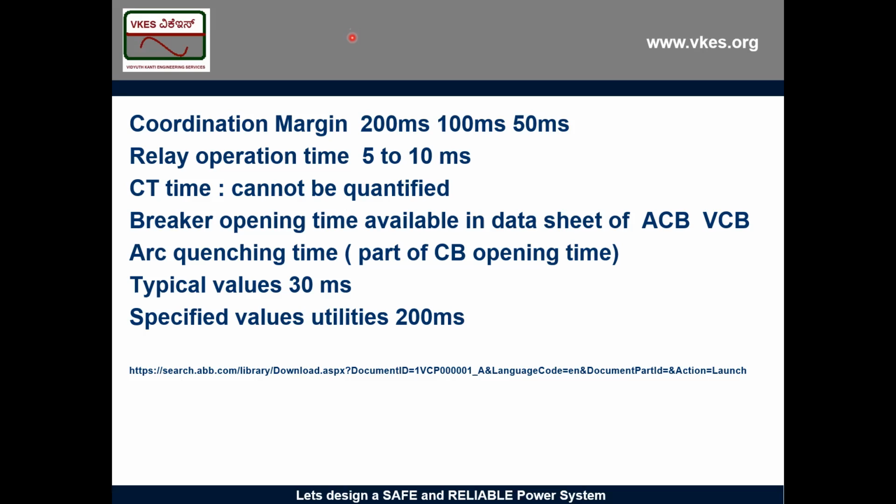Mr. Vijay, what I'm seeing on the screen is similar to that. But in BS7671, the total time to trip, I think it says around 1 second or something. So the total should be 1 second, from the transformer secondary to the final node, after adding all those. Okay, sir.